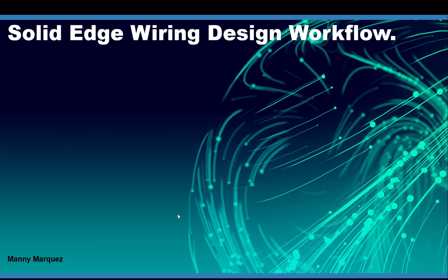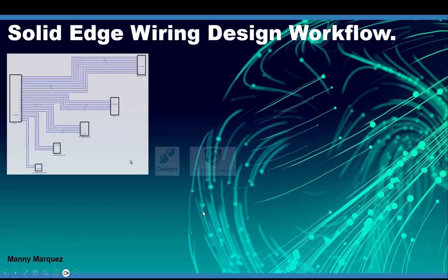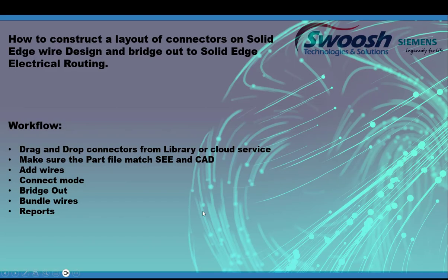So, on today's topic, we will talk about Solid Edge wiring design workflow, how to construct a layout of connectors in Solid Edge wire harness design and bridge out to Solid Edge electrical routing. The workflow goes, basically, you start with the drag and drop of the connectors from the library